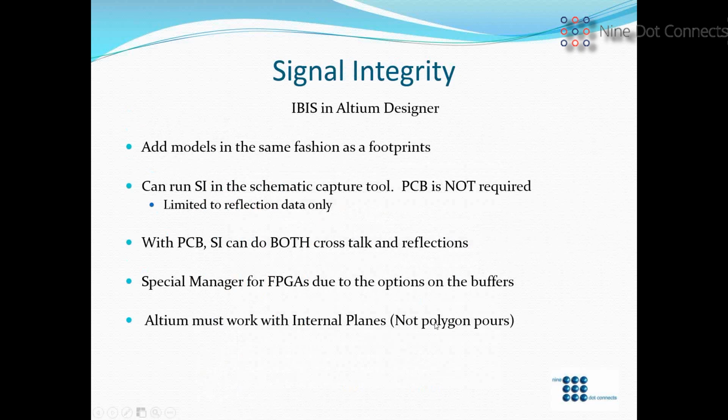But keep in mind, too, it may sound like, hey, why don't you just do it? It'd be easy. But again, there are going to be people who are going to try to handle signal integrity by doing polygons on the top and the bottom, which is going to be very fragmented, and that's going to cause a lot of effort for Altium to do a tremendous number of calculations.